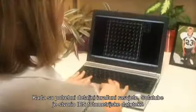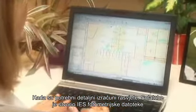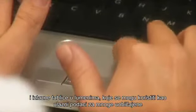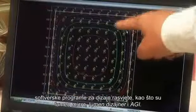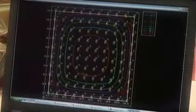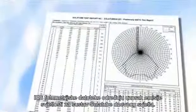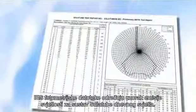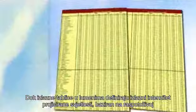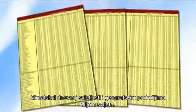When detailed lighting calculations are required, Solatube has created IES photometric files and lumen output tables that can be used as input data for many common lighting design software programs, such as Lumen Micro, Lumen Designer, and AGI. The IES photometric files provide the pattern of light emissions for a Solatube daylighting system, while the lumen output tables provide projected light output intensity based on the available climatic daylight in geographic areas throughout the world.